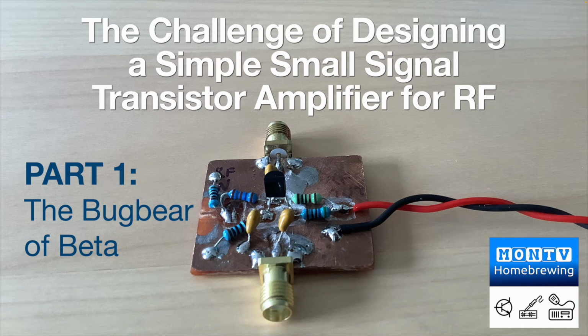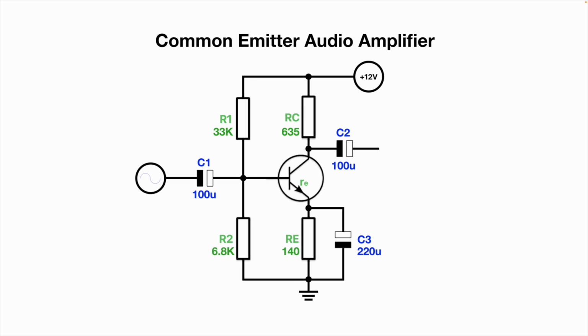So let's get started. The challenge of designing a simple small signal transistor amplifier, but for RF. And that is the one that I built, which you'll see more of in a bit. Now, this was the original design of the common emitter stage, the first stage in that audio amplifier that I built in the video that I mentioned before. Now, obviously, if we were to use a similar thing for RF, then we're going to have to do something about these capacitors, because these capacitors are large.